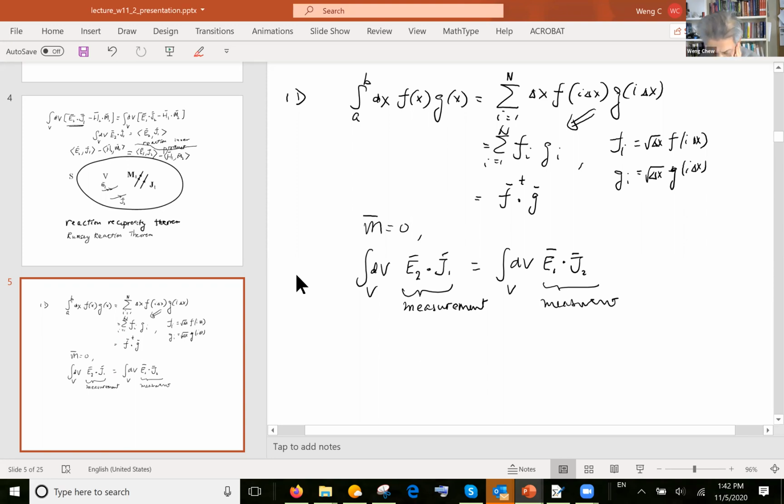Okay, and it becomes more obvious if J1 is a Hertzian dipole. If J1 is a Hertzian dipole, then it would be something like I1 L1 delta(r - r1), pointing in the l1 hat direction. So you can write a Hertzian dipole current that way. And then you can also write J2 as a Hertzian dipole pointing in the l2 hat direction, I2 L2 delta(r - r2).